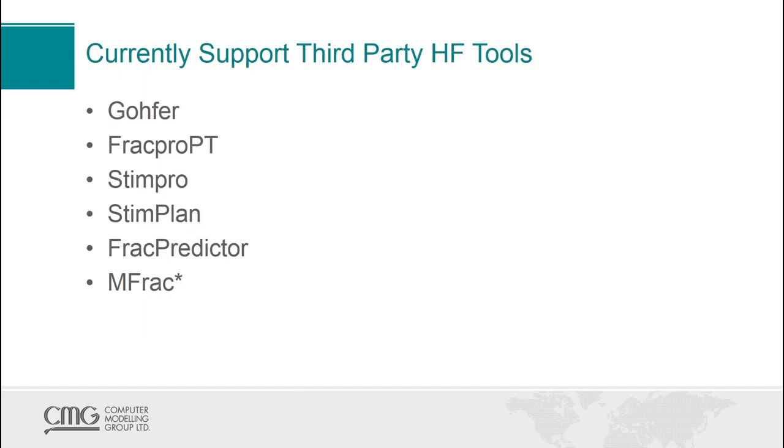Okay. Next question is, thanks for the presentation. My question is how to handle the problem of fracture closure. Okay. Well, I think closure is something usually associated with the end of the pumping job and what happens when you try to keep proppant from dropping down in the reservoir, etc. Maybe, though, I think what we're talking about here more is the effect of changing effective stress on the proppant permeability and so on and so forth.